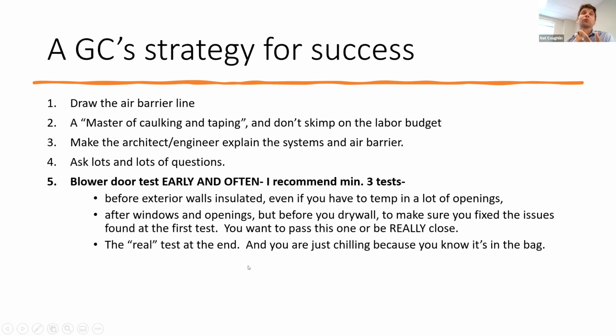And then you do a second one once your whole envelope's closed in, but before you've drywalled. And by then, you're hopefully going to pass that test. And then when you do the third test, you're just making sure you didn't screw something up. At the wiring school, we passed our second test. And so the third one was nice because we felt like we had it kind of in the bag, and we caught a few little issues around some final things that we had to fix.